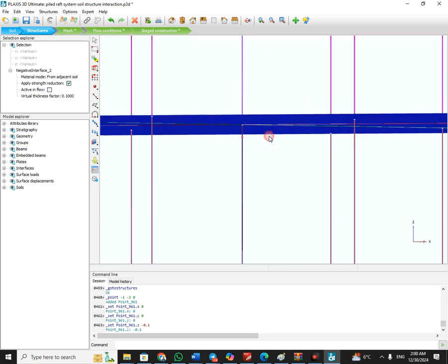Double click again on it, select it. Okay, very good. Select the point, give it 10 centimeter in the X. That means 10 centimeter off from the pile. So the point is going to be completely isolated, completely independent from the pile and the foundation plate, just surrounded with the soil around it.